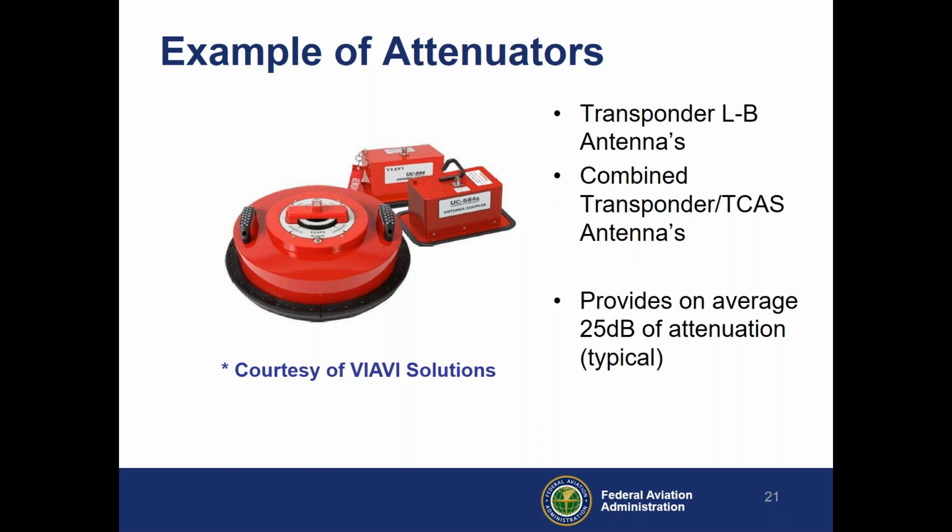Mm-hmm. And we've had many discussions with a lot of shops out there that continue to get picked up by the ground station and rebroadcast, and many of those have been just not having a proper seal, or they didn't get transponder 2 shut off, or it's been a lot of cases like that. There have been cases where just using the coupler itself works, and they do have a good fit and follow all the proper procedures.